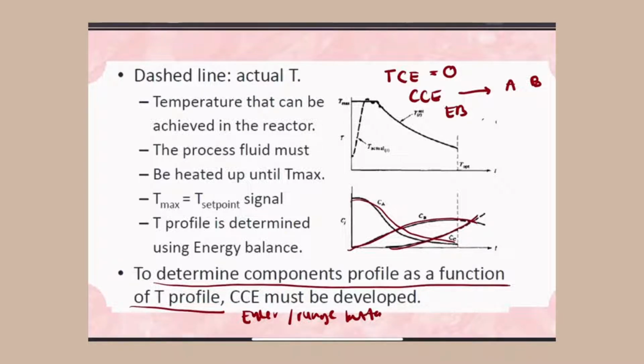And the energy balance also needs to be plotted on the same graph. For example, if our initial T is 30 and then it starts to increase, this is because we supply the steam. However, we cannot let the temperature get too high because we don't want the product to degrade. So we also need to know when the degradation of the product happens. And then from here we can see that the graph is starting to decrease. This is because we start to supply the cooling water.